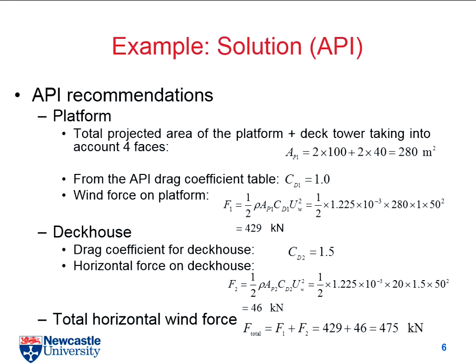It means we also need to think about the force acting on the side. So that's the reason why, after you know the side surface area, we need to add this part. Because we have another side, we need to add them together. So the first part is for this acting area and the back area, and this part is for this side and the other side. Okay? That's the reason why you can see a calculation here, and we are following the API rules.